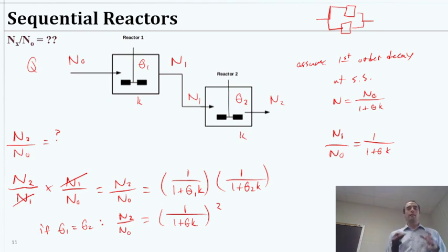We could think about it in the same way if we had plug flow reactors. Our overall balance for plug flow reactors is often a little bit different. And in some way, if you think about it, a plug flow reactor is more like a hose. So if you sequence one hose and then another hose, it's kind of like you just extended the one hose, right?